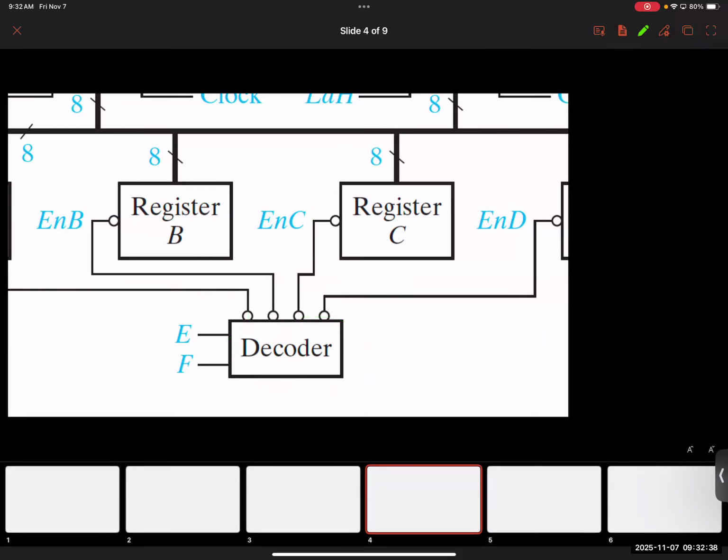So very simple logic. If you're wondering why you would even need a decoder, maybe because of this. And this is the foundation for computer architecture, essentially. You need to activate registers. Once you enable this register, remember, there is a clock, right? It doesn't happen right away. The clock ensures everything is synchronized. We can keep count. Did the clock edge come? Yes. Okay, now I'm ready to disable the register. Just disable it and enable the next one, and so on.